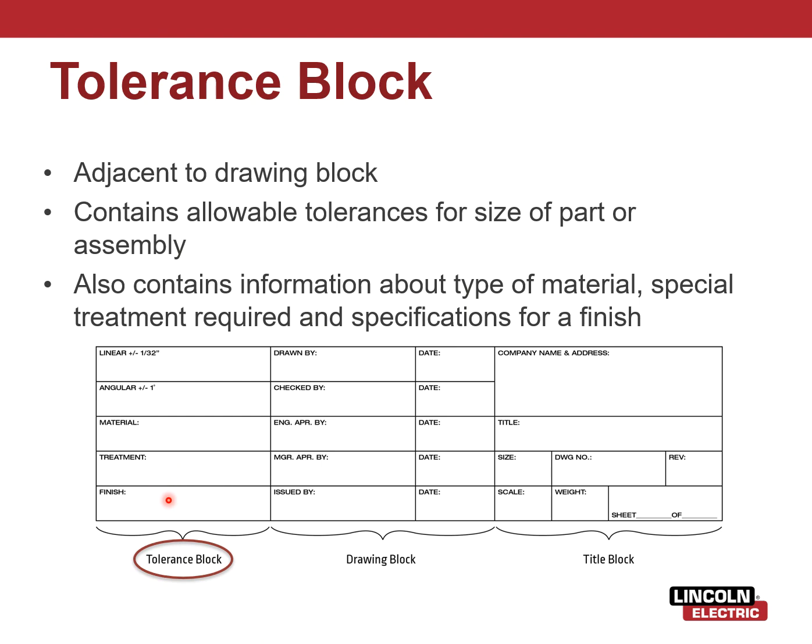And then the finish. So does this need to be machine finished? Does this need to be ground? Does this need to be sandblasted, right? What do we want this looking like before it leaves the shop? Okay, so that's what you're going to find in the tolerance block.